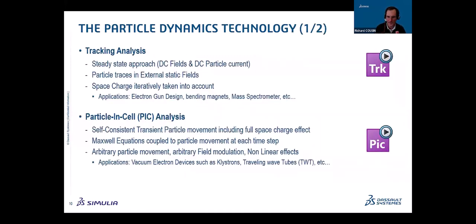Let's now move on to the different set of solvers that you can use for your dedicated applications. First of all, let's start with the tracking solver. The tracking solver is a static solver where you can use external fields, an external E and an external B field, in order to compute the trajectory of the particles.